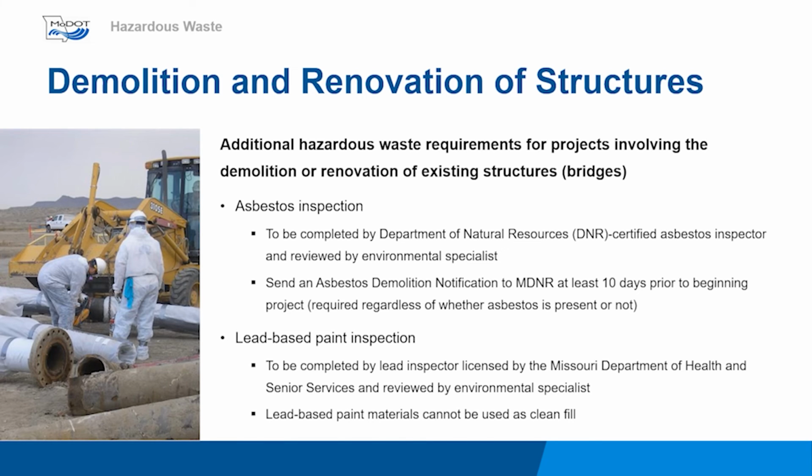If lead-based paint is documented on a structure that will be affected, the LPA should keep in mind that these materials cannot be used as clean fill. Documentation of the asbestos and lead-based paint inspections, as well as reports and lab results, should be uploaded to the RER for review by MoDOT.